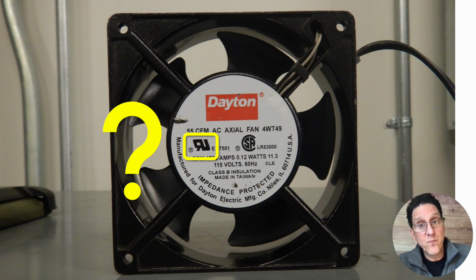But that same piece of equipment might also say, do not install on GFCI protected circuit. That does not mean you can omit GFCI protection for a receptacle that piece of equipment is plugged into, if that receptacle is required to have GFCI protection per 210.8, for example. You can't omit GFCI protection on a receptacle. What that means is that piece of equipment can't be plugged into that receptacle.